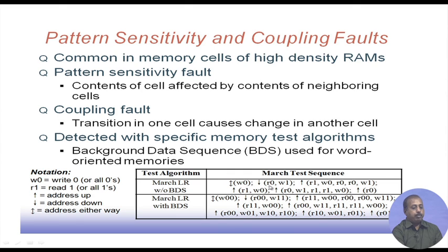Then once it is done, I will come to the next element. The next element tells that from the highest address to the lowest address, we first do a read operation, and in the read operation we are expecting a 0 to be read, because previously we have written a 0. After reading this 0, that cell's content is changed to 1. So it is basically checking whether these zeros have been written properly, and then trying to change this 0 to 1. Once I have written the entire memory, now in the increasing address direction I try to read the value, and I am expecting the value read to be 1. Then I write a 0 there, then do a read operation on that cell expecting 0, and another read operation.